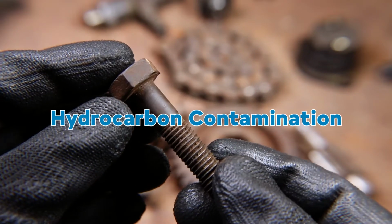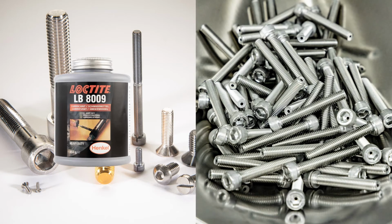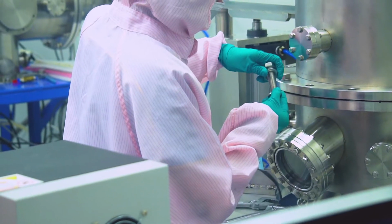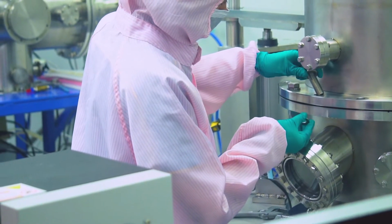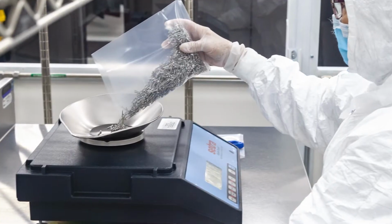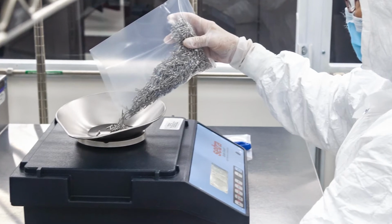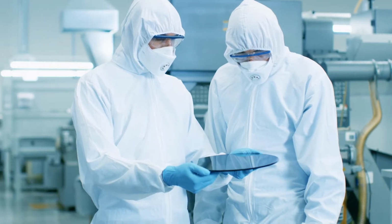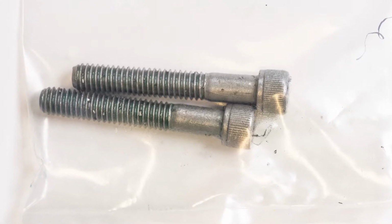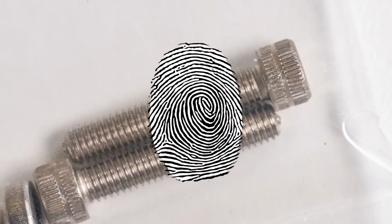3. Hydrocarbon contamination. Hydrocarbon-based lubricants, such as oils and grease, can be a major source of contamination and are difficult to remove. They have very low vapor pressure and will spread throughout a tool quickly, requiring both lengthy and costly cleaning to fully remove, not to mention potential product, wafer or substrate defect, or outright failure. Hydrocarbon contamination could be from original part or subsequent manufacturing processes, or even a fingerprint.